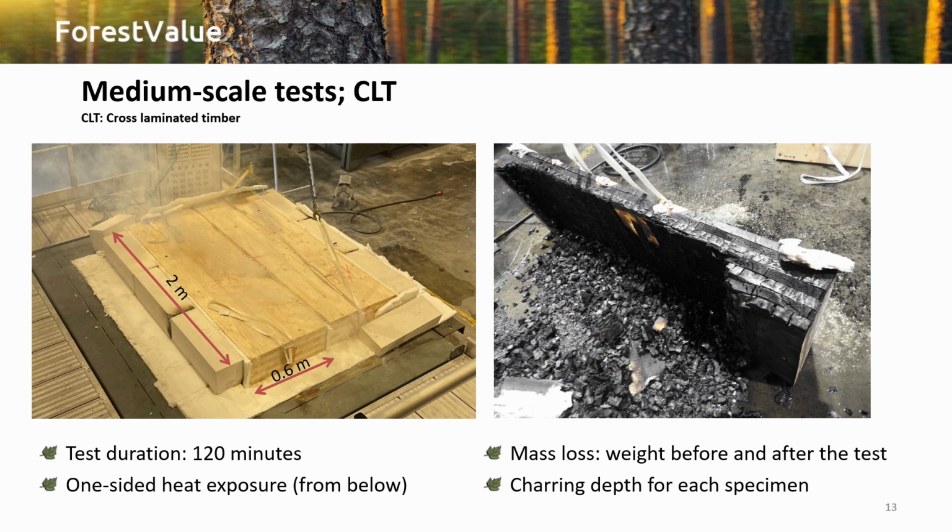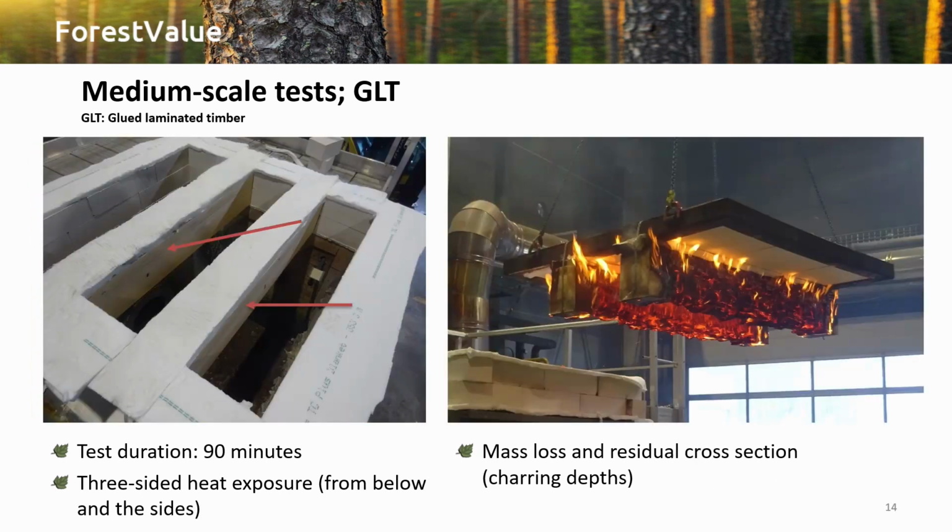It's one-sided, also only from below. And for these tests, we measured the mass loss and also the charring depth. To the right, you see, of course, after the test, and the element is standing on its side.